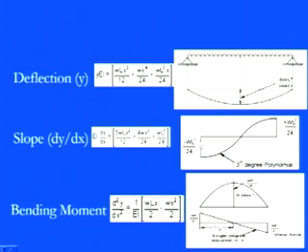So you see here, minus to positive, it varies in this particular way, and it has the characteristic of a third degree polynomial, and it always passes through a zero slope where the maximum deflection is. So it is exactly these things.